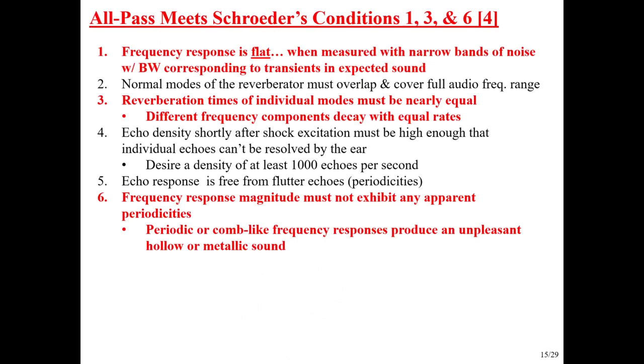So let's see, where are we now? Well, we've picked up 2 more conditions. So we did have 3, and we retained that because we kept all of our poles at the same distance from the origin. But we've got a perfectly flat response because it's an all-pass filter.